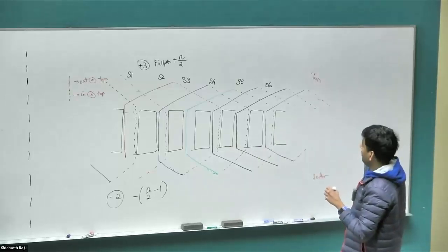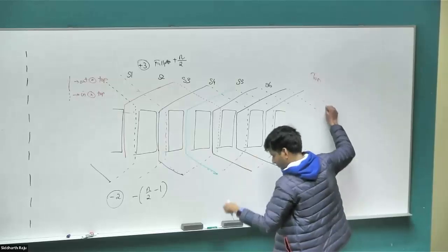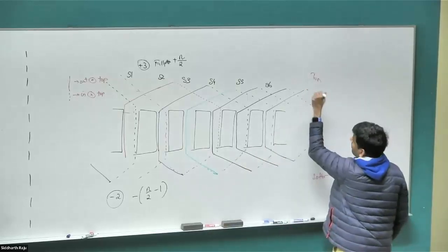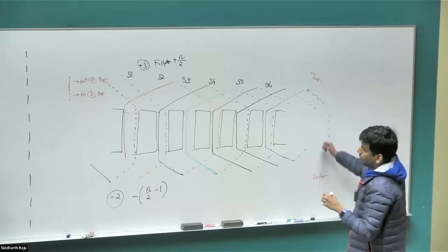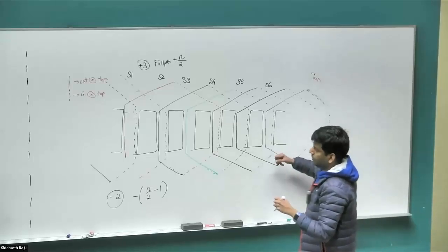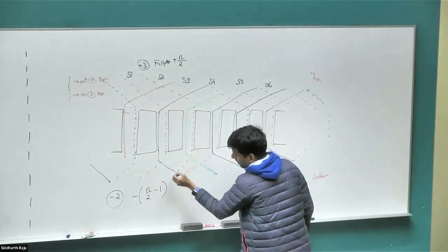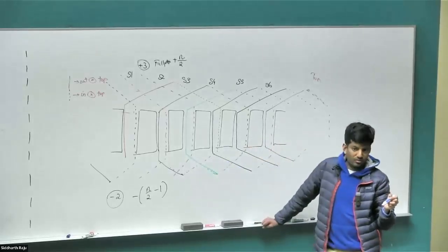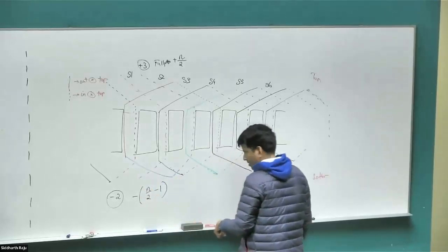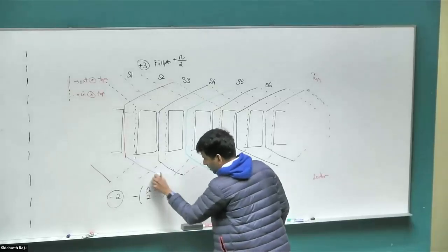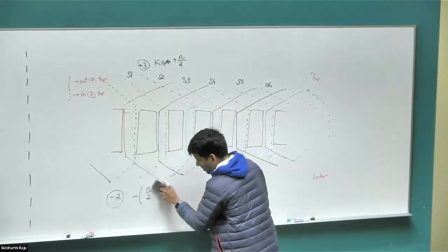And finally, this ends up terminating in slot 1 that we have here. Sorry, I should use a different color. That is green. So from slot 6, it needs to go back to the top and goes into slot 3. And where does slot 3 terminate? In the back, slot 1. So n by 2, just 2 slots behind, and it terminates into slot 1. Symmetric.